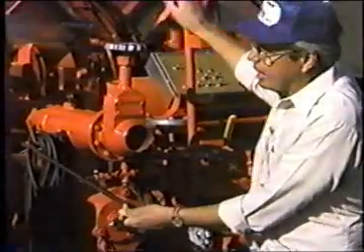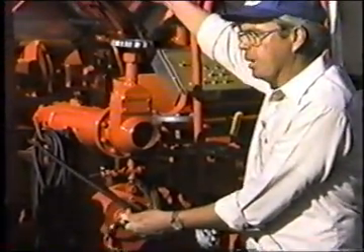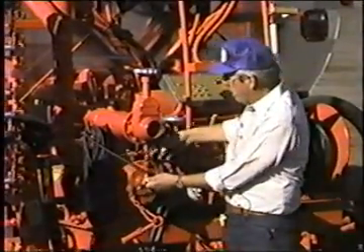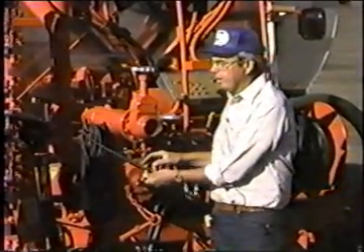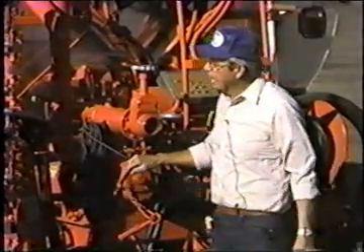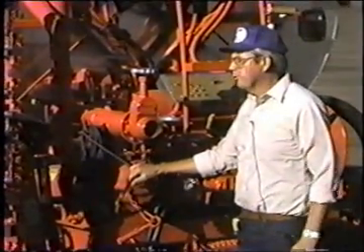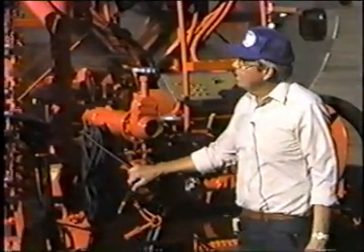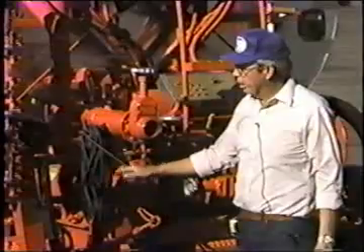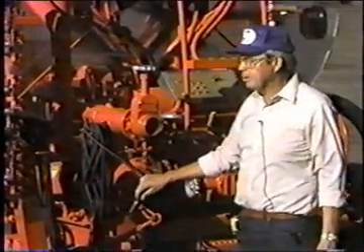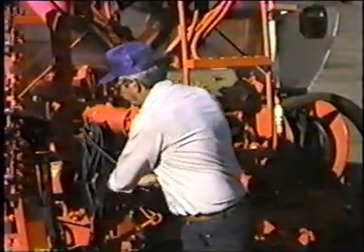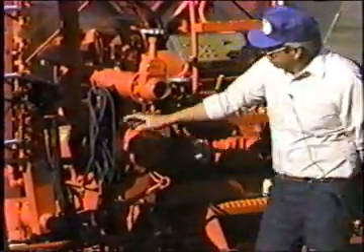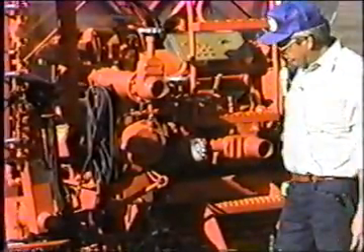If this truck didn't have a diesel burner, it would have an electric pump up near the fuel tank, and you go up there and turn the electric pump on. Same thing back here. Open this valve and spray it down. The cleaner you keep the back end of this thing, the easier it is to work with, the easier it is to work on. You can see if you've got mechanical problems. Everything continues to function well. The diesel acts as a lubricant. Keep it washed down. That's an important part of it. Get all done, coil that up, tie it up so it doesn't get away.